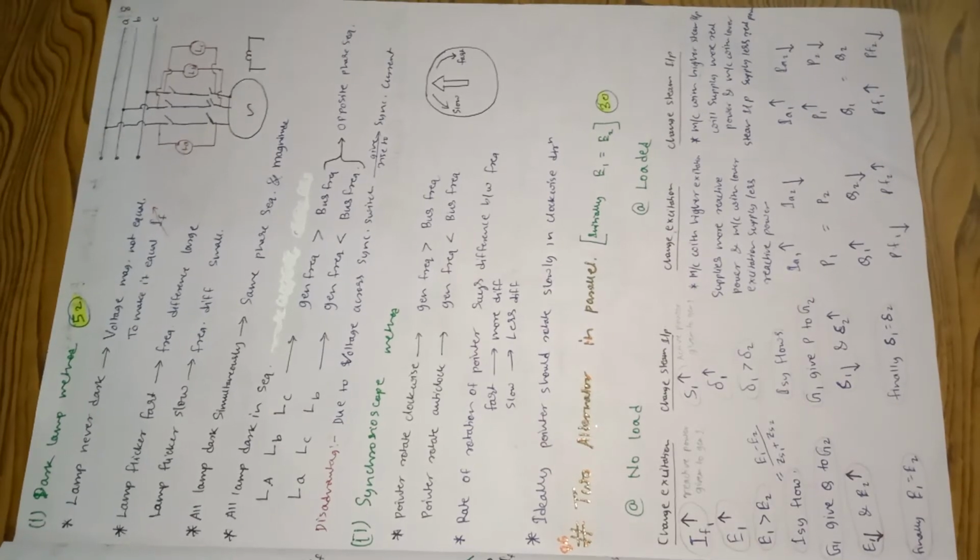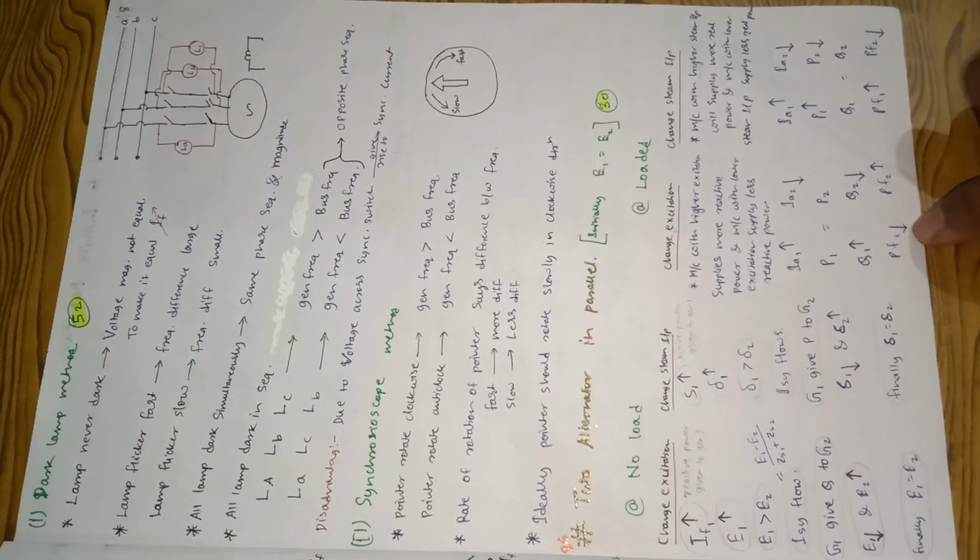Okay, you can use the formula of power factor to see why this power factor is decreasing and why this one is increasing. You can understand this by the logic that power factor is equal to P upon S, active power upon apparent power. See, active power is the same in both, but here apparent power is increasing due to the increase in reactive power. If the denominator is increasing, then what will happen? Power factor will decrease.